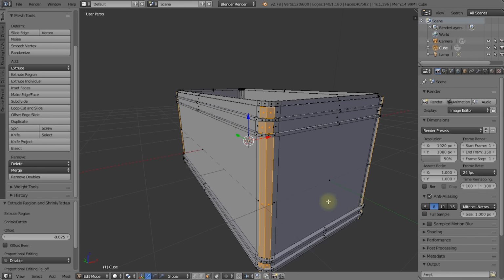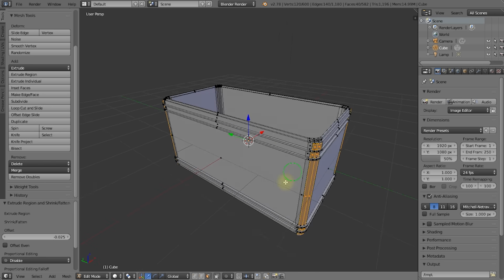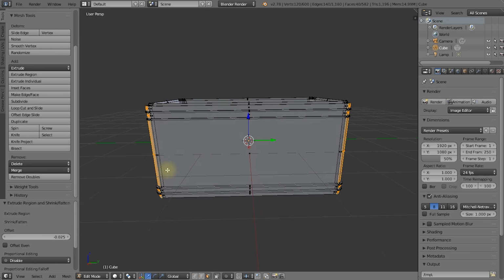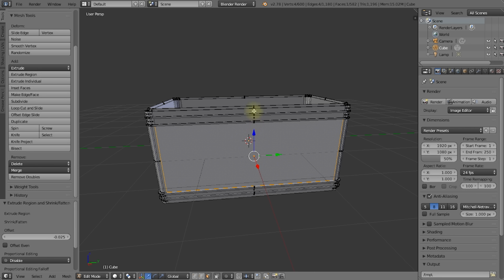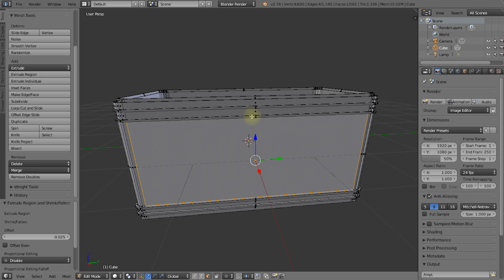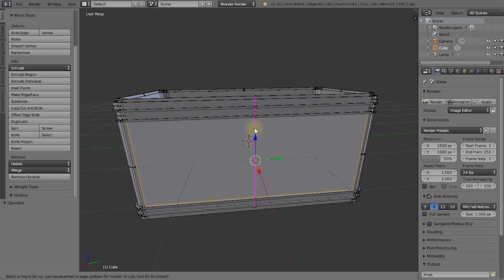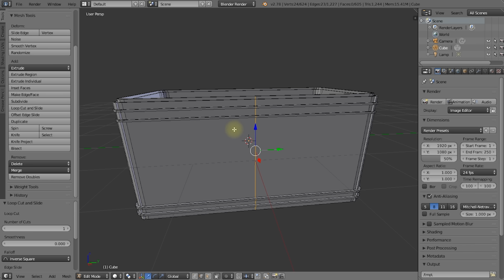So now that I've got that extruded, the last little bit I want to add to the body of our trunk is just a little bit of detailing right down the middle. As before, the sides are just these ginormous faces. There isn't actually any edge here for us to bevel out. So let's add another loop cut. And if you've forgotten how to do that, press Ctrl and R, or in your tools, simply select Loop Cut and Slice. And let's simply click and place this right there without moving it.